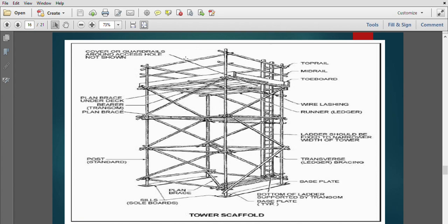And if you see an upright installed outside of the post, as in my previous Aramco exam, it is a major fault. Now this is compliant because all top rails and mid rails are installed inside the post.